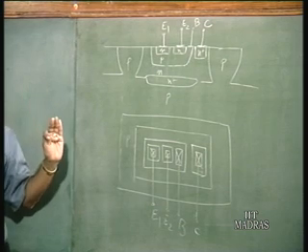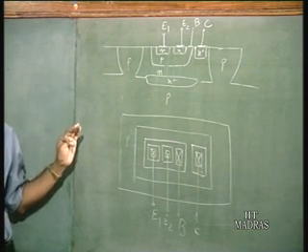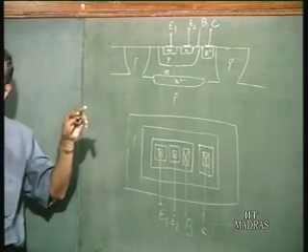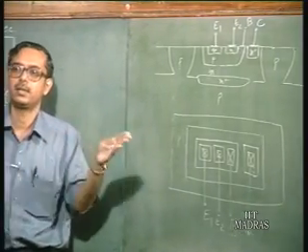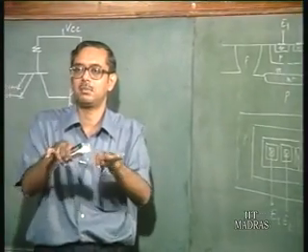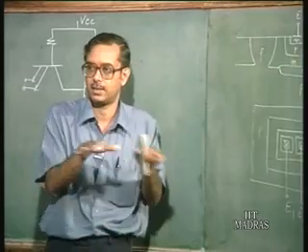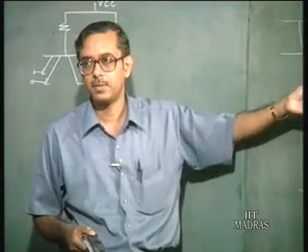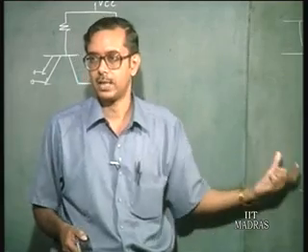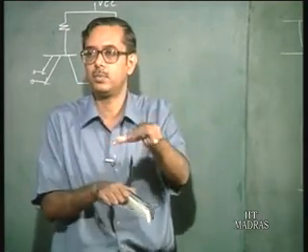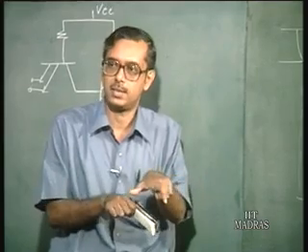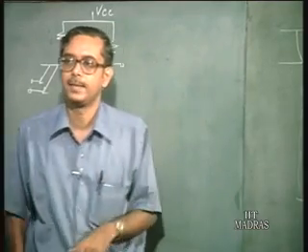Basically, just to repeat, a multi-emitter transistor is a transistor with a common collector base junction, but separate emitter base junctions. So you can consider them as transistors in parallel. There is a space saving if you have a multi-emitter structure rather than having to fabricate two separate bipolar transistors.